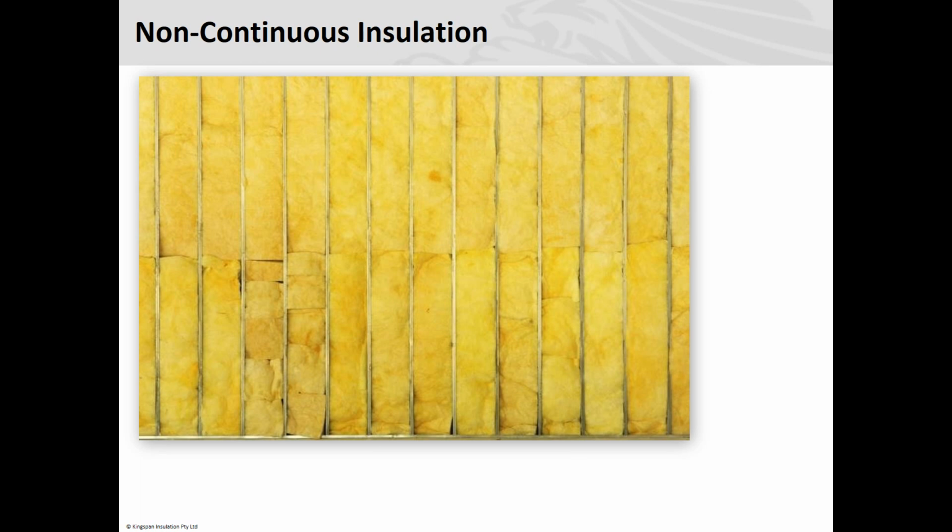One of the ways they're trying to tighten this down is to introduce blower door testing. Basically, for a building like this, they'll close up all the doors and windows and put a large canvas bag over the door. They'll have 1, 2 or 3 fans on that canvas bag and pump air into the building. They'll work out the volume of the building and how many air exchanges an hour it will have. A good building will have probably 8 air exchanges an hour, and a really poor building maybe 20 air exchanges an hour.